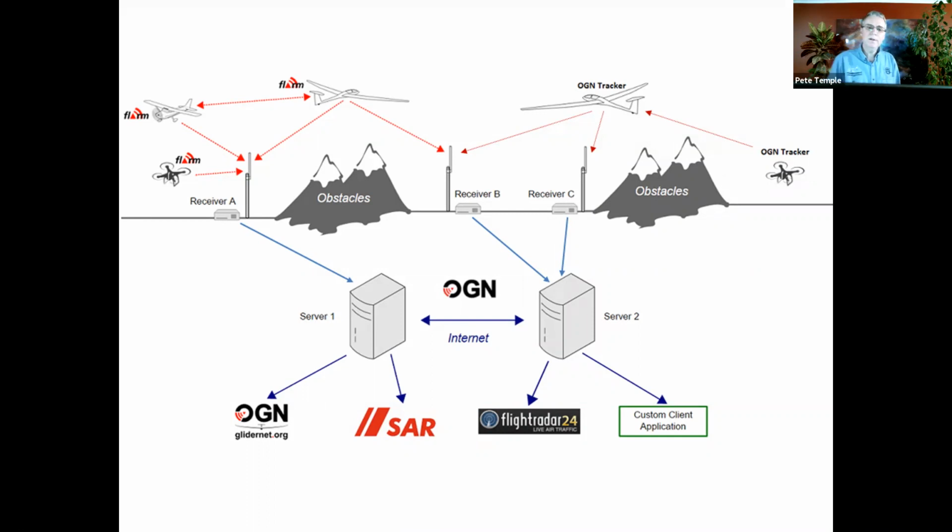Now, the innovation that enabled my flight last November to be tracked is that smart chaps took this FLARM information, which is fairly short range. It's 3 to maybe 10 kilometres. I have occasionally seen 15 kilometres, but generally it's sort of 1 to 6 kilometre range. It's pretty short range. But if you have a ground receiver, it can actually receive that signal up to, say, 150 kilometres. There's one of these receivers installed at Waikerie in South Australia. There's numerous others around Australia at the moment, and we're in the process of rolling out a bunch more in South Australia.